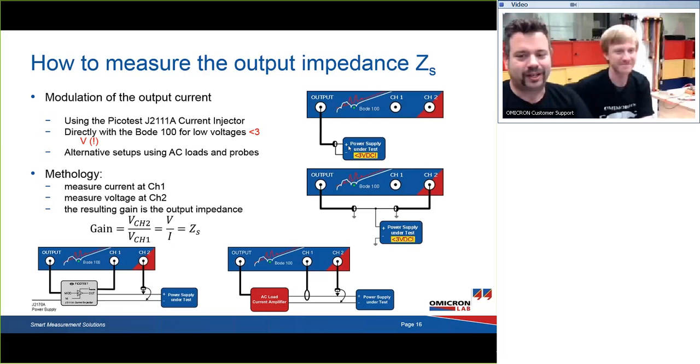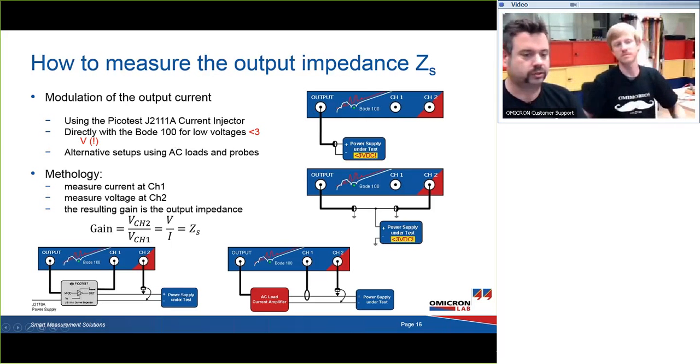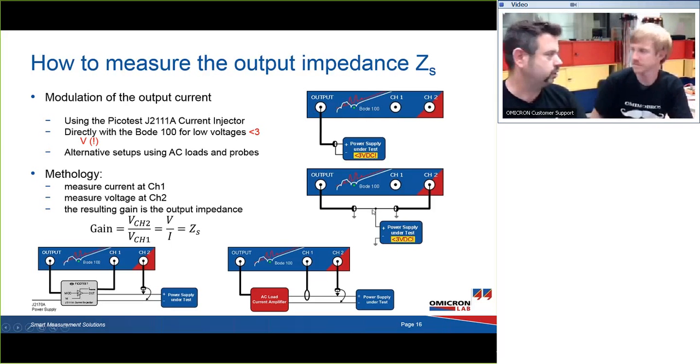So in any way, the point is when you do this one-port measurement, as we explained yesterday in our impedance seminar, it's recommended for impedances down to 0.5 ohms, but usually a power supply has a much lower output impedance, and therefore we can use the shunt-through method, which allows us to measure even lower. But again, the limitation applies that you should not go above 3.3 volts.